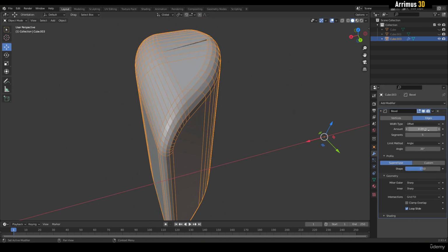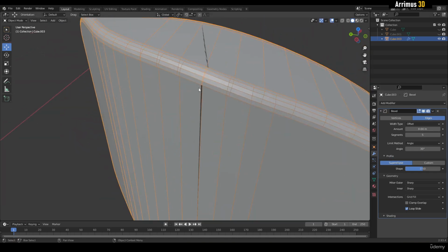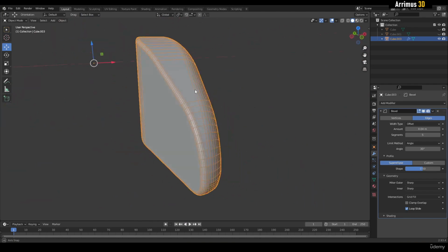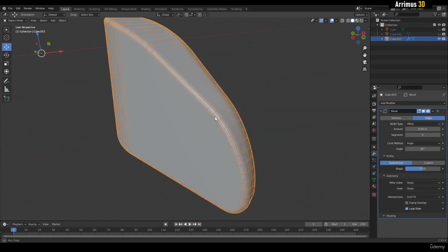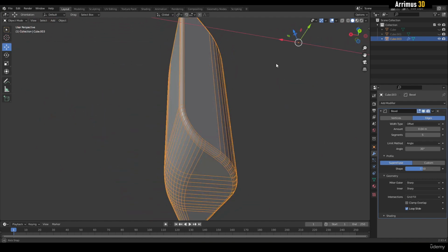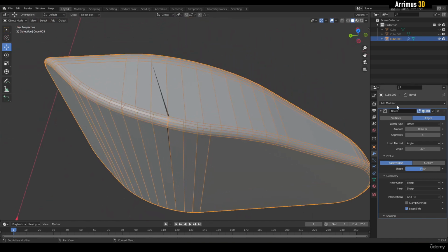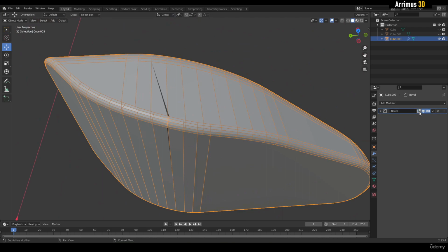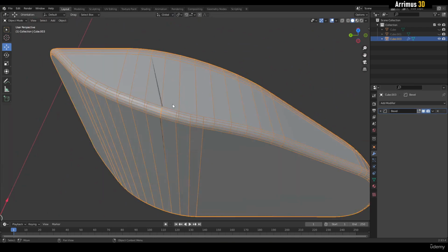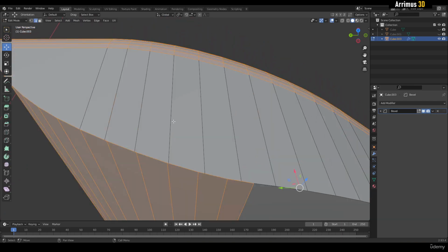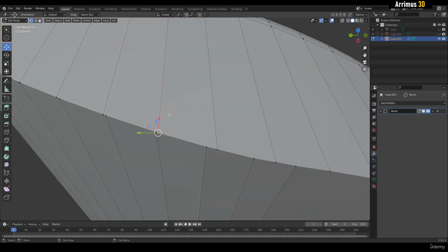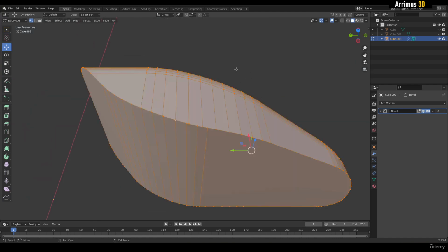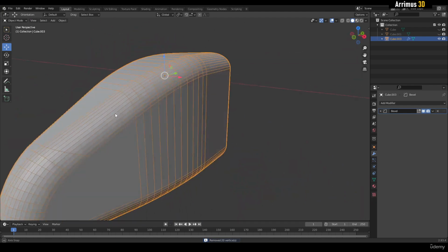All right. So, when you try to achieve large fillets, you start getting all sorts of shading problems, which of course you need to work out. I mean, you see, it's not too bad, but still, you can get much larger fillets with a CAD program much more easily. Now, how would you fix this real quick? Well, what I would do is turn off bevel. And so I press tab. Okay, so obviously, I think two vertices close together are causing this. We can, for example, press A to select everything. Press M, use by distance to merge this. Open this up, and perhaps just increase this. Okay. As you can see, that solved it. Kind of a quick fix.